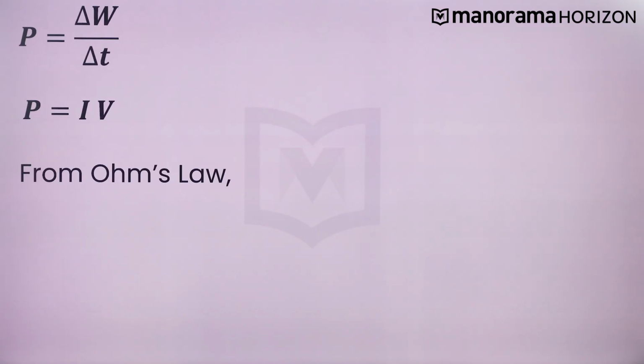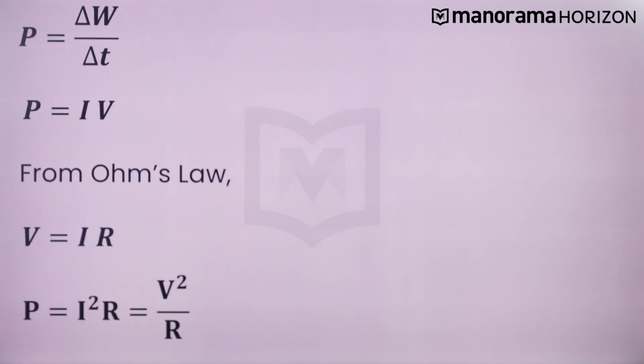So since P is equal to delta W by delta T, and we know that P is equal to I multiplied by V, and from Ohm's law, we also know that V is equal to I times R. We can perform a substitution that gives us P is equal to I square R, or P is equal to V square upon R. Now, these equations are of critical importance in understanding why we require those transformers and why we require those very, very high voltages.